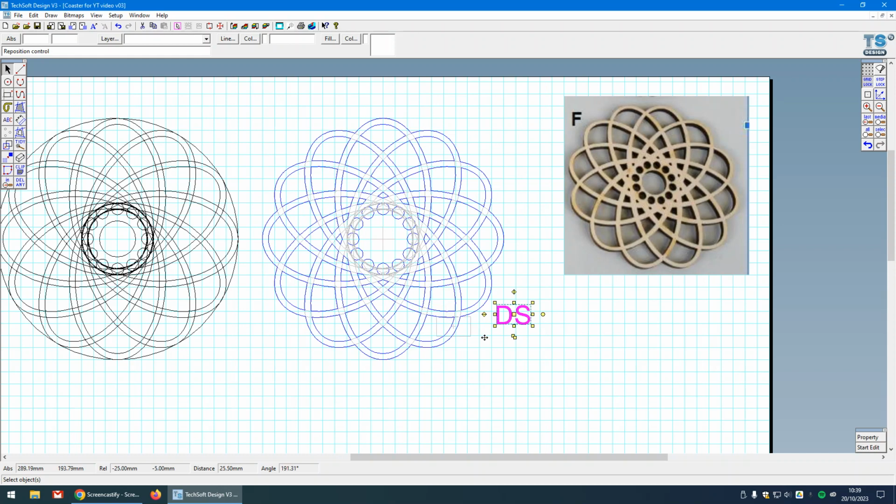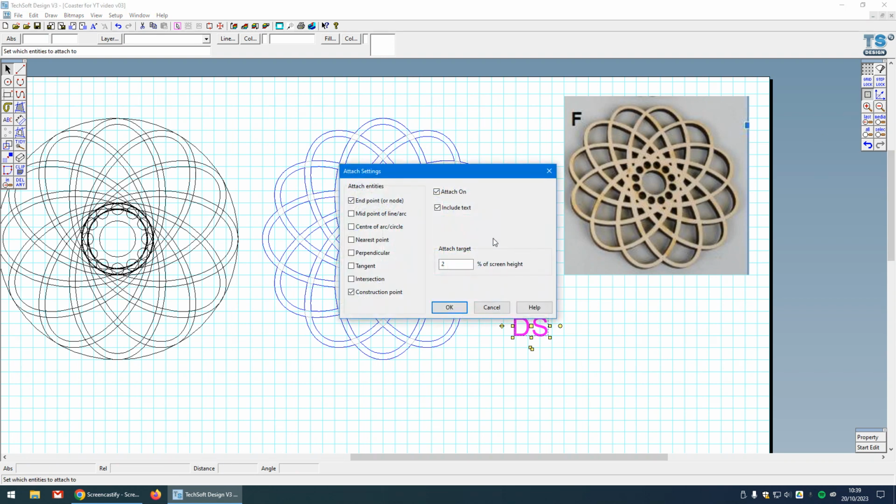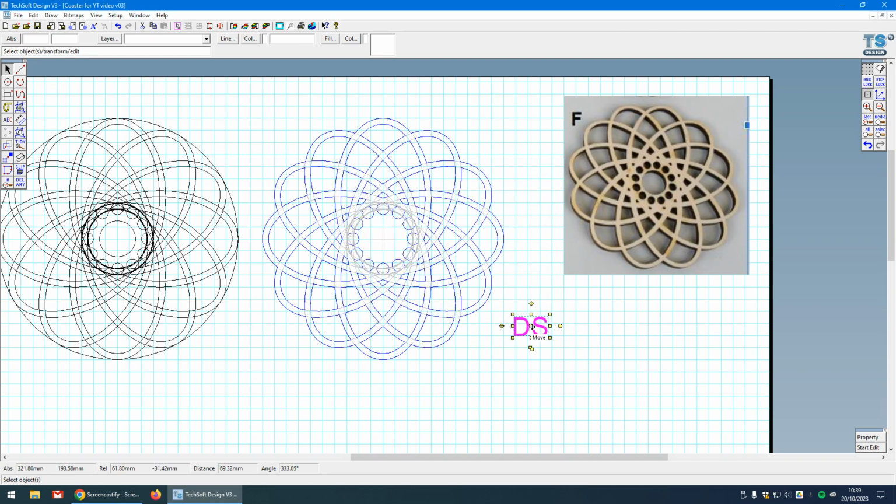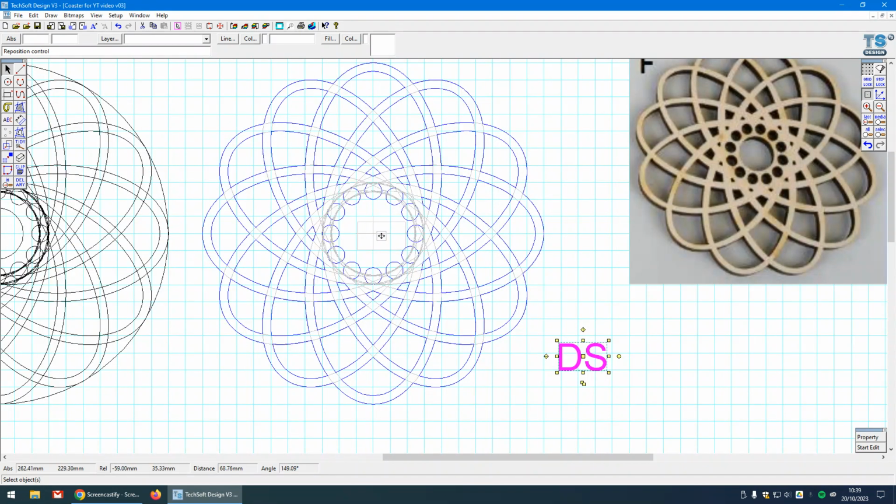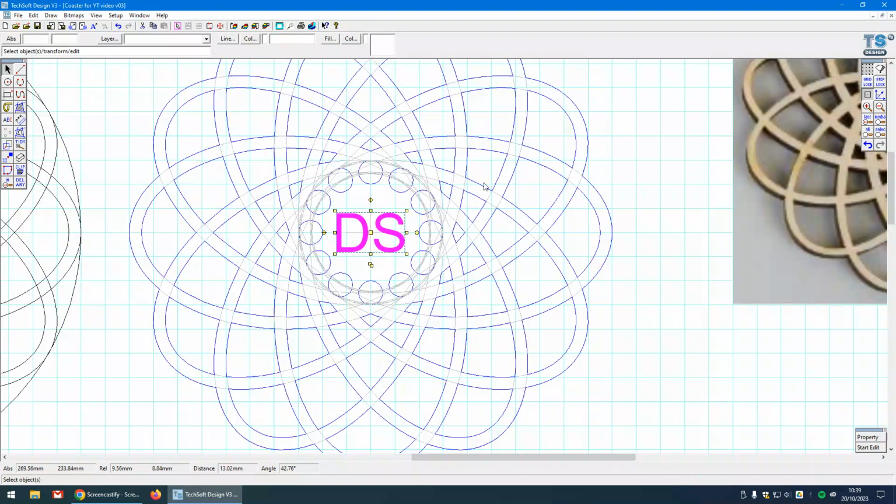so that it's going to be aimed right on the center of this coaster. So to do that, I'm going to come to the Attach tool. Now, at the moment, the Attach tool is going to snap it onto the end of that line, or it's going to get confused, so I'll just turn off gridlock there. I'm going to right-click on the Attach tool. I'm going to change the Attach Entity attributes from endpoint to midpoint. And then now, as I mouse over this, as long as I have the attach square encompassing the center of the cross there, it should snap right into the middle.